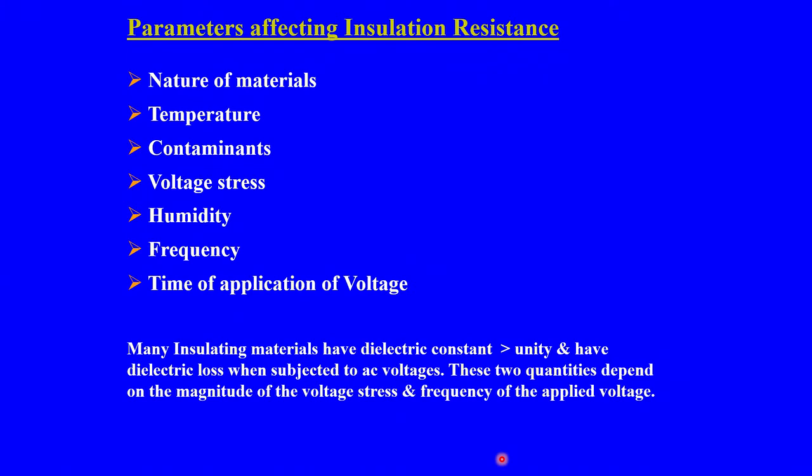So, many insulating materials have a dielectric constant usually greater than unity and have a dielectric loss when subjected to AC voltages. So, these two quantities particularly depend on the magnitude of voltage stress and the frequency of applied voltage. So, two important factors to be noted here.